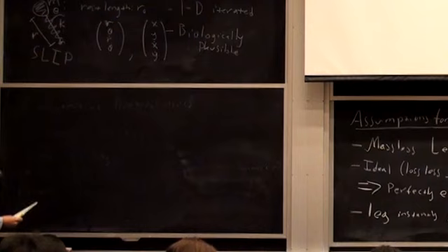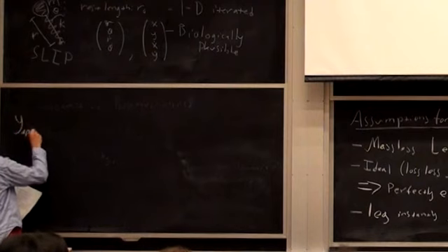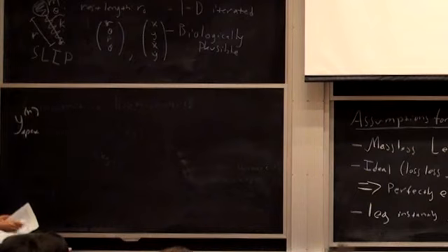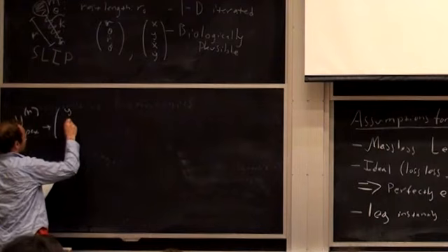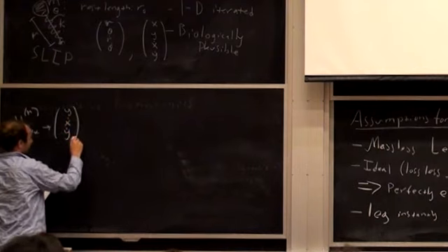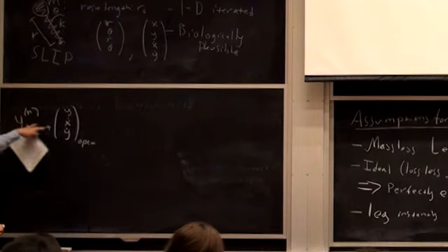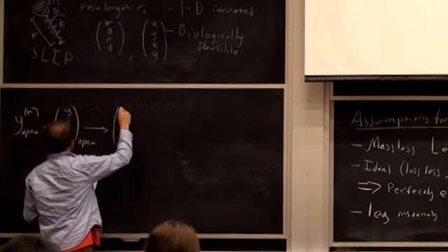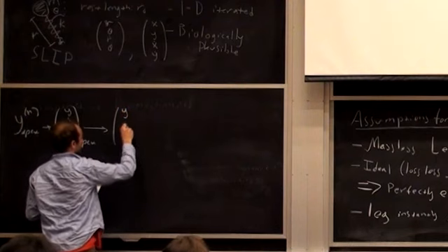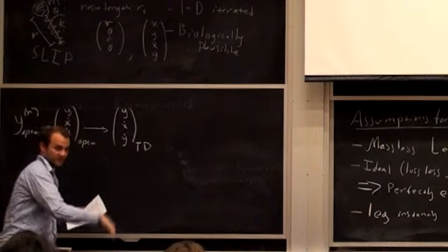All right. So we go through this transition. We go from apex to apex. What we can look at is we have y apex at n. Then we need to figure out how that translates into the y, x dot and y dot at that apex. So we need to map this one piece of information into all of these. Then we can map that into the y, x dot, y dot at the touchdown, so when it comes in and hits.